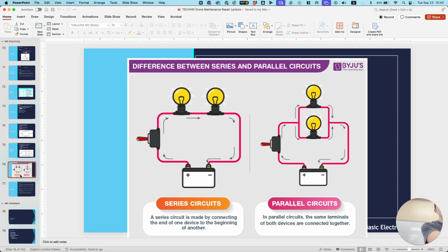What is this thing? Is it series or parallel? It's parallel, right? If you were to crack open the inside of this thing, there's just a metal bar going down both sides, so you can have multiple things plugged into it. The more things you plug into it, the more current it's going to draw. The voltage still stays the same. That's why if you plug too many things into a certain outlet, sometimes you trip the circuit breaker. The voltage is still the same, but you have surpassed the current that the breaker allows.